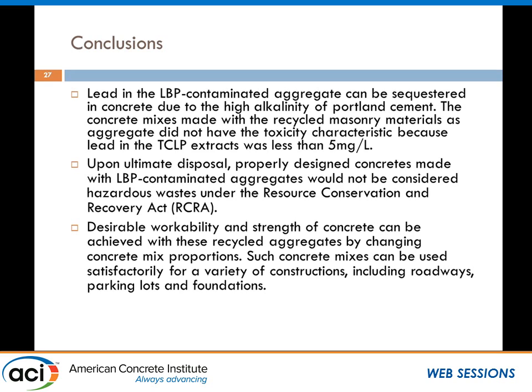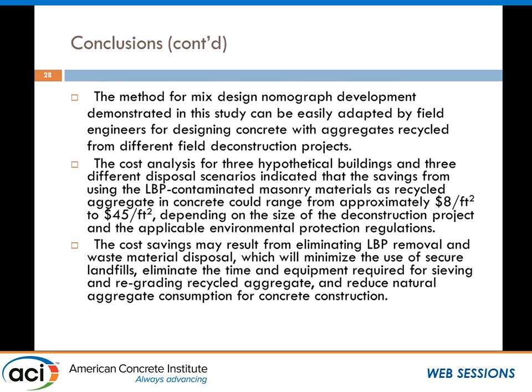Desirable workability and strength of concrete can be achieved by appropriate mix design. Of course, we can optimize this by combining it with natural aggregate. Again, this was not in the scope of that research. The method of mix design, the nomograph we developed, can be used to design concrete based on the specific aggregate that you use. Cost effectiveness: we can save from like $8 per square feet to $45 per square feet based on different scenarios and different cases. The cost saving resulting from eliminating lead-based paint removal and waste material disposal could be very beneficial.